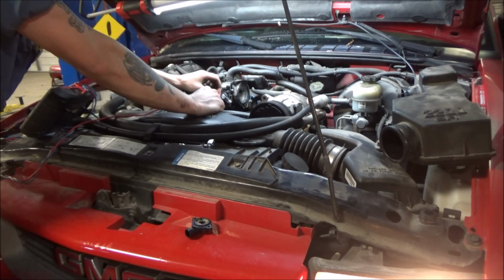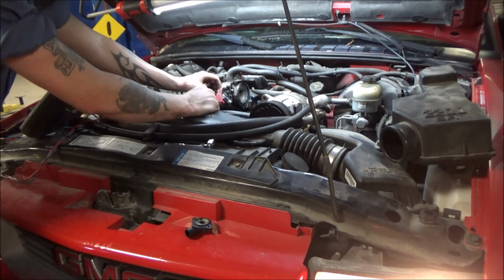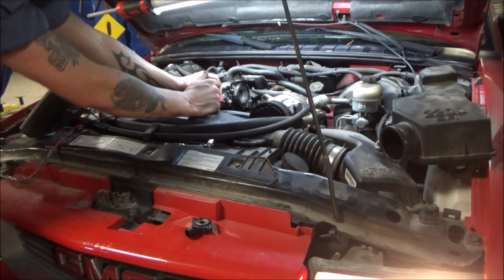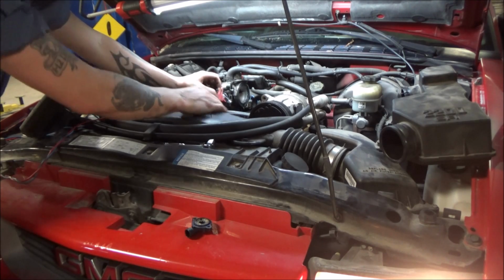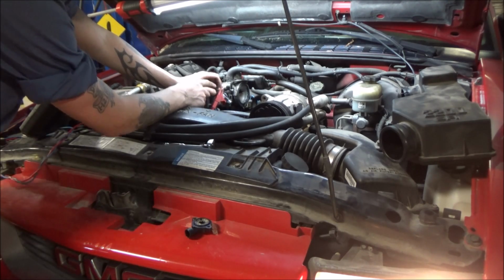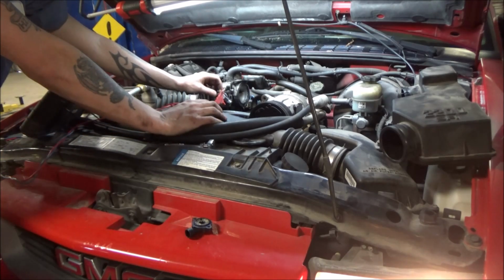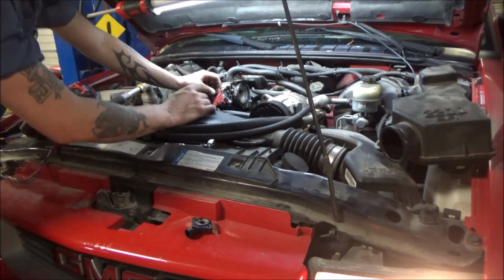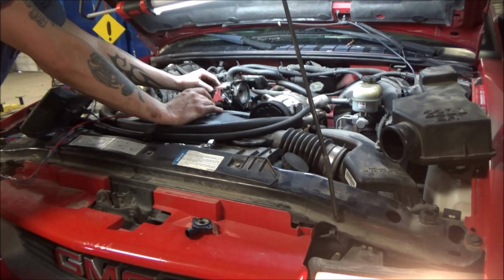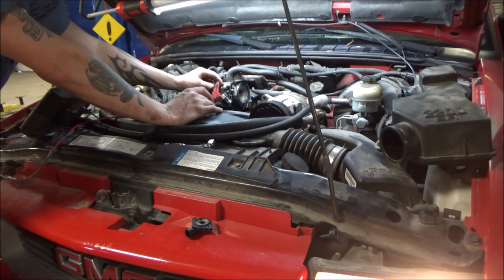You can also use a test light to do this. Take your test light, place it to battery positive, and just pump that reference circuit into this throttle position sensor voltage. As far as jumping the reference to the signal, you definitely want to use that resistor in place in case there is a short to ground on this. If there were a short to ground on this signal wire, guys, what this engine computer would be seeing all the time is 0 volts, without a doubt.